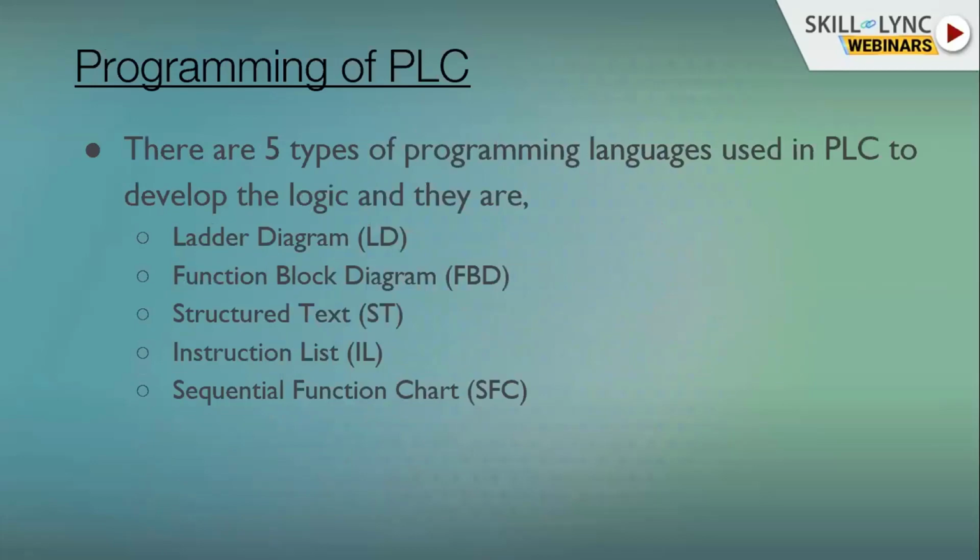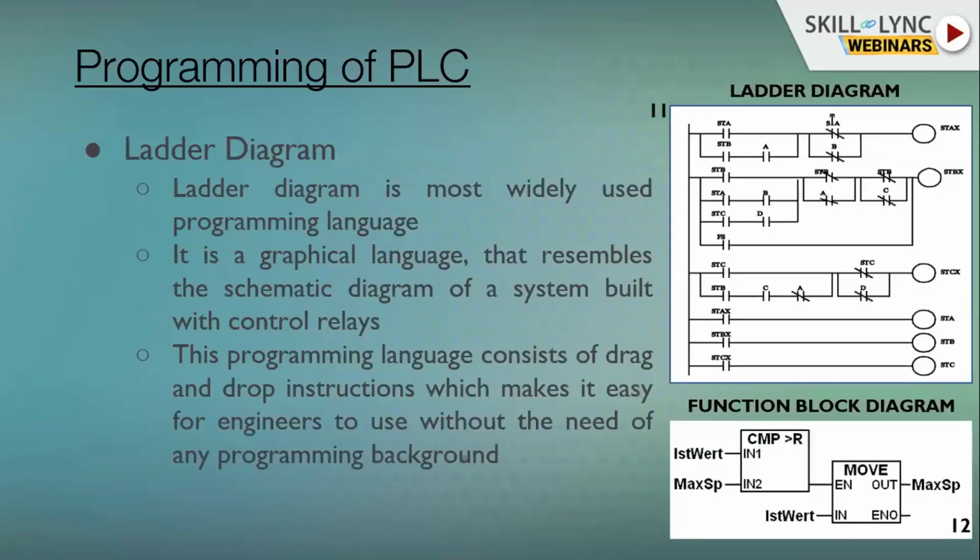Let's have some idea of the programming languages used in PLC programming. We have five types of PLC programming languages: ladder diagram, function block diagram, structured text, instruction list, and sequential function chart. Most widely used is ladder diagram, and it is most popular because it resembles the hardware relay logic we would otherwise make using a relay control panel.